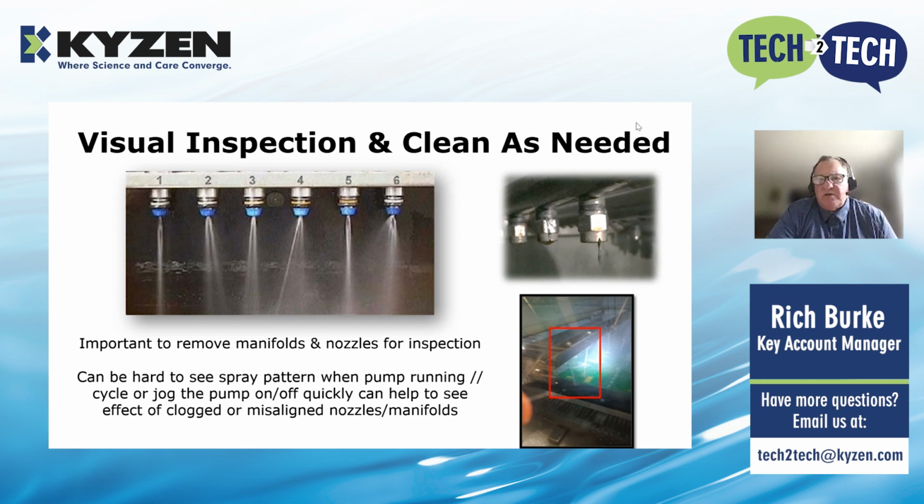I would say follow the recommendations from our suppliers, but in essence, what we want to do is visual inspection. That can involve looking inside of the machine itself. As you can see in this lower picture, it's highlighted in red. In this example, one is able to actually see a nozzle or manifold that's not spraying well because something is clogging that nozzle or manifold. In many cases, it's hard to do. The inline systems have a lot of spray and atomization, so it can be difficult to actually see that happening. And in terms of a batch system, in many cases, they don't have windows or viewing ports.